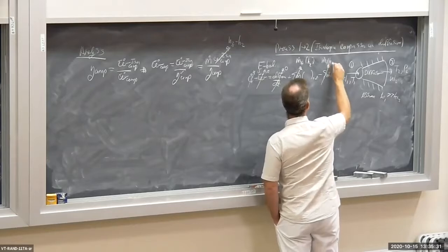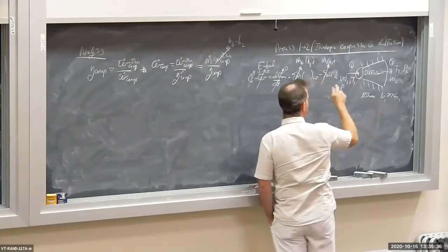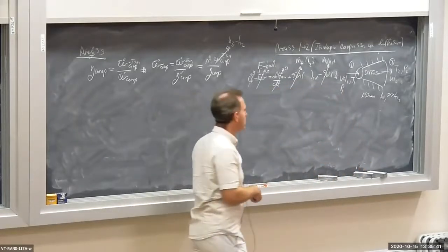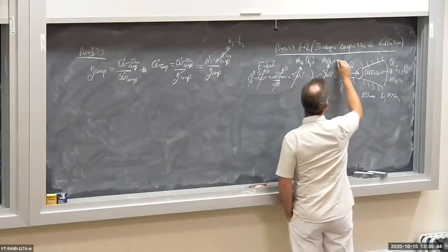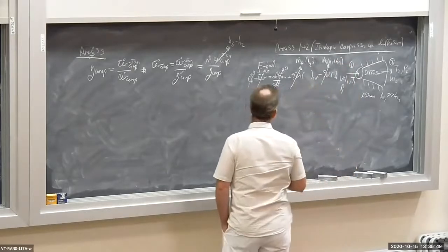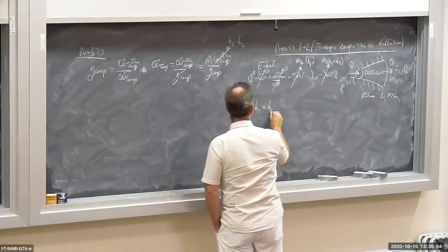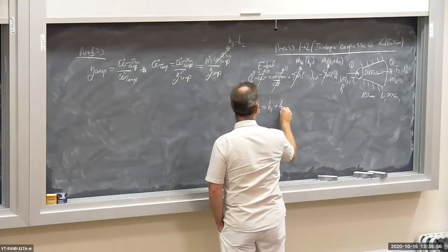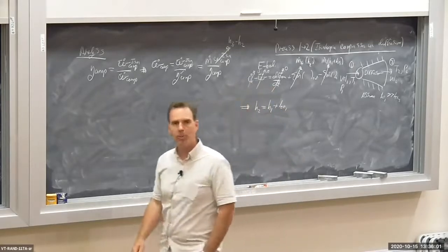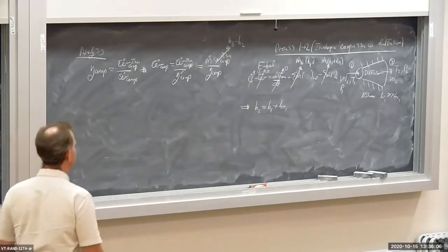I have H at the inlet plus the kinetic energy. I can't neglect kinetic energy at the inlet. The purpose of the diffuser is to convert kinetic energy into an enthalpy change, so I have to have the inlet kinetic energy term, KE1. So H2 is equal to H1 plus the specific kinetic energy at the inlet. What happened to the mass flow rate? I'm assuming m dot 1 is equal to m dot 2, so I got rid of the mass terms.